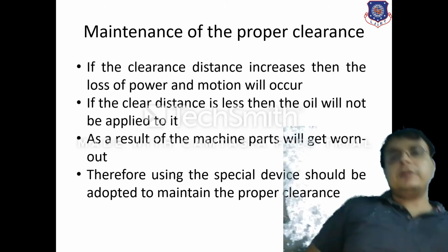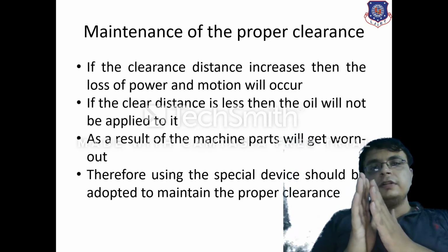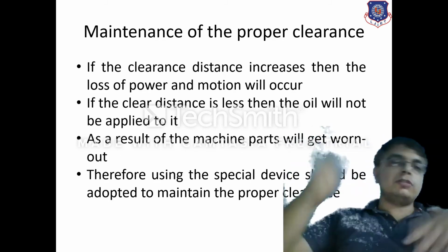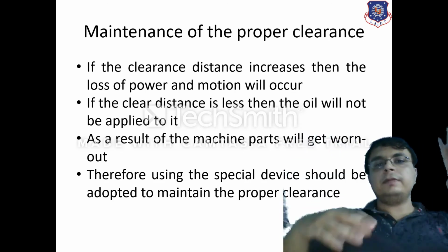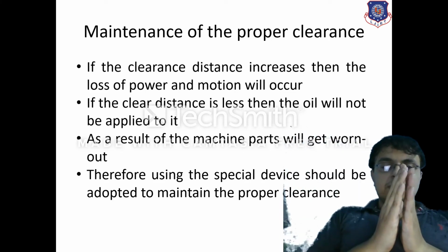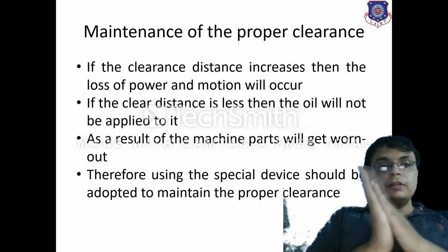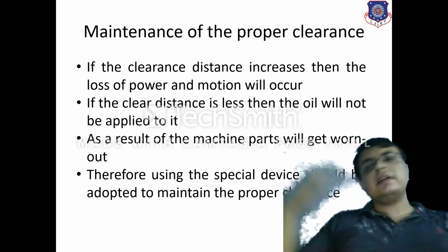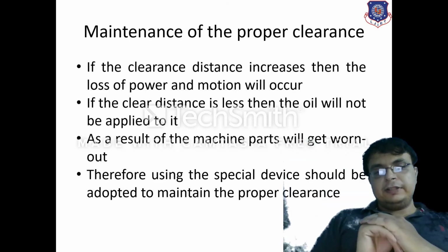Maintenance for the proper clearance. We all know that if the clearance between the surfaces increases, then there will be the loss of motion and loss of power. And if the clearance between the two surfaces is lesser, then the more will be the contact of the two surfaces, and as a result of this, the wear rate will increase. The wearing out of the machine will take place.